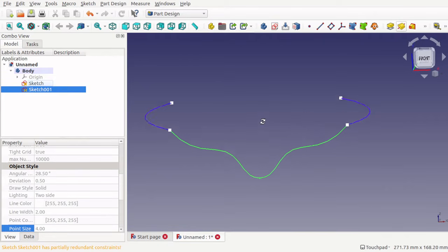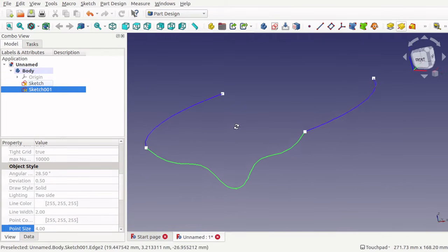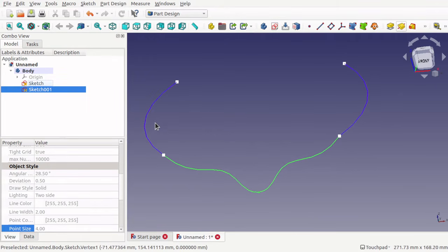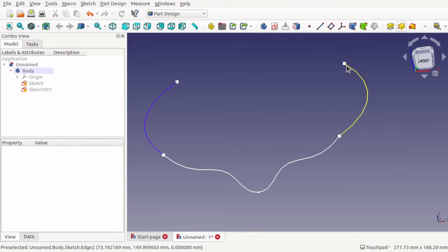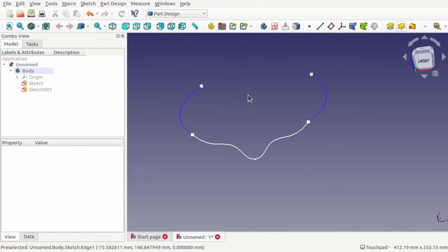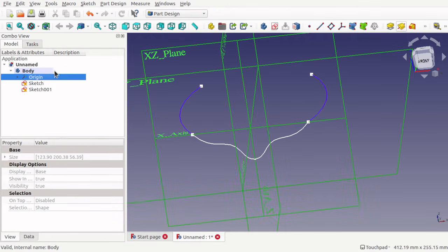So we've got the back and the sides, and now we need the profile at the front. So we've got 1, 2, which will become a surface, and then at the moment there's two rails here which will become one. So there's one rail here. The supporting lines will be called rails. So we need to place a rail along here, and this is where we need to create a datum plane, because look at our origins.